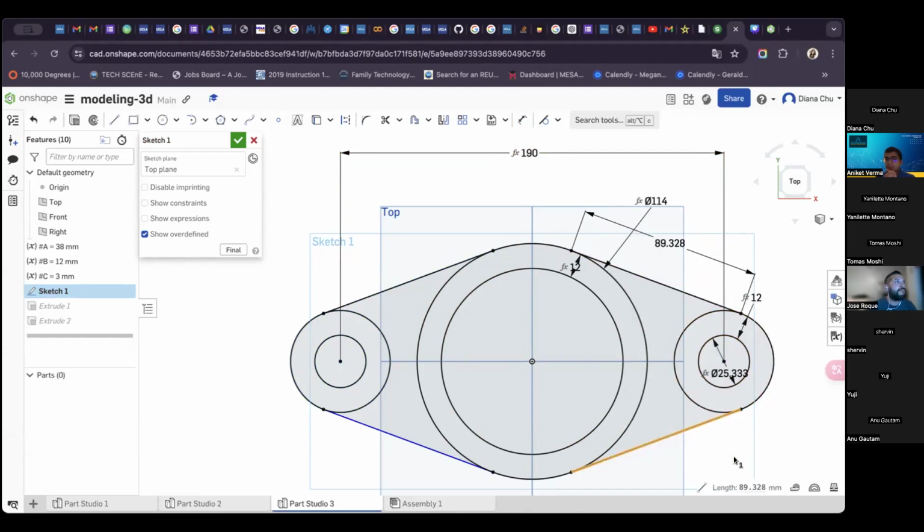That means the length of those lines wasn't defined. So if you define that, you're fine. You shouldn't have to define the length of that line. It's more likely something to do with your circles, but that also works as a solution, because it seems like all your relations are correct. Yeah, that works.